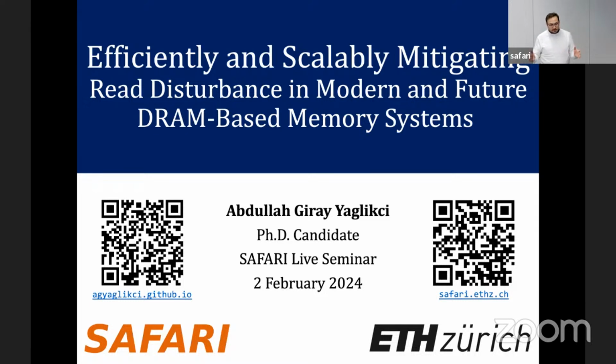There are some mechanisms, for example HiRA, that observe the activation counts in a very accurate way and perform the mitigative actions, and it's also implemented in the memory controller, but it needs to maintain a lot of metadata, and there is a lot of overhead of storing that metadata in the DRAM chip and then fetching it to the specialized cache in the memory controller. Fetching everything creates some overhead as well. Some other mechanisms implement a lot of counters in the memory controller.